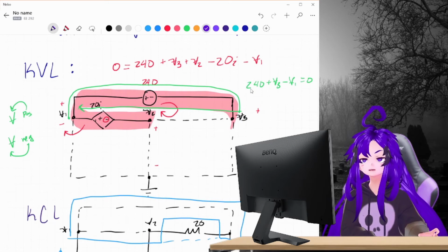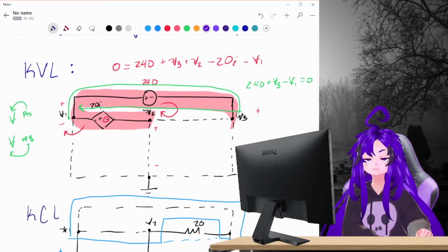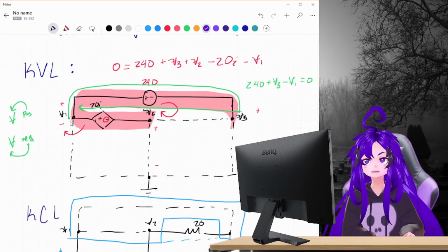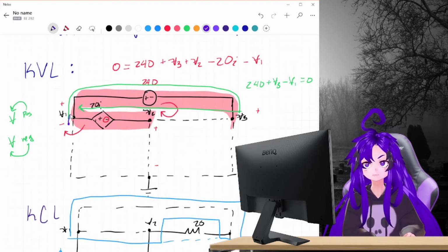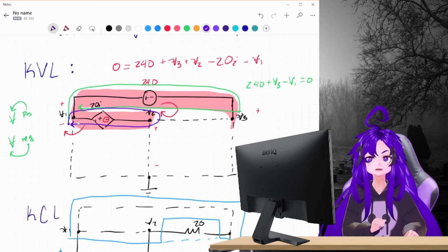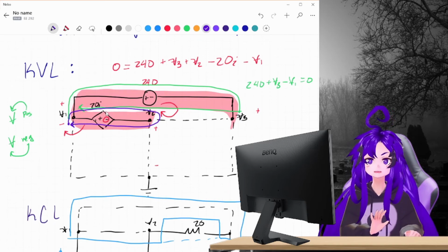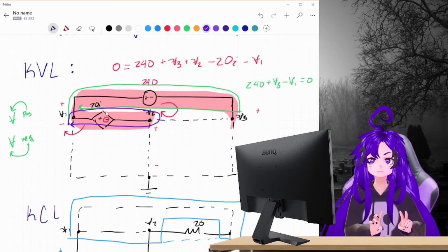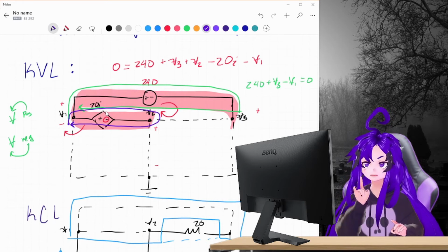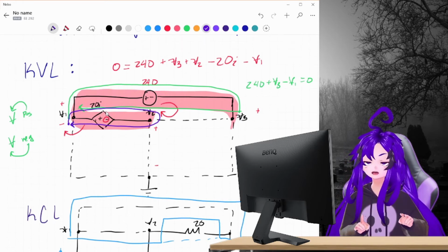You might be asking, okay, boss, but how are we gonna connect 1 and 3 and 2? So the next thing is we're going to do the same thing around this voltage source. And we're gonna start here, and we're gonna loop around and into there. And so basically what you'll notice is that if you pretend, not that there are two supernodes, but if you pretend there is one supernode per voltage source, then you get these relationships.